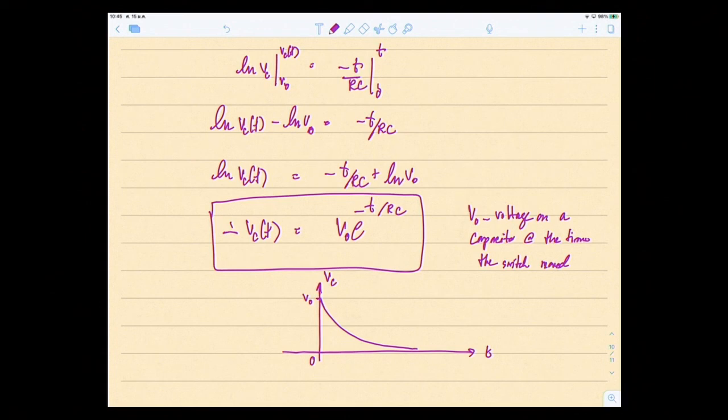So this is exactly, if you imagine it, your battery on your phone, right? After you fully charge it, you unplug it. At the beginning it says 100%, and as you use it, it drains out through R, in this case. The battery uses up its energy, and the voltage drops until by the end of the day, if you didn't recharge it, it would reach 0. Okay, so this is how it looks like.